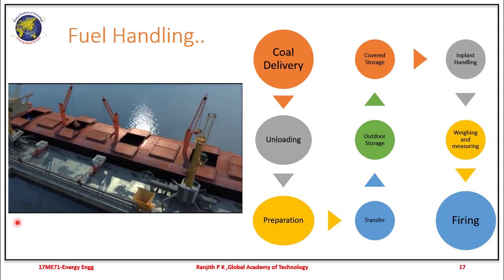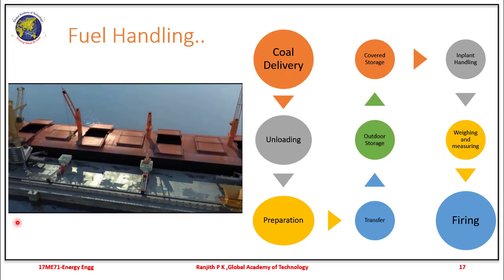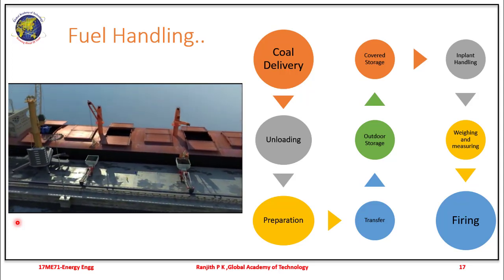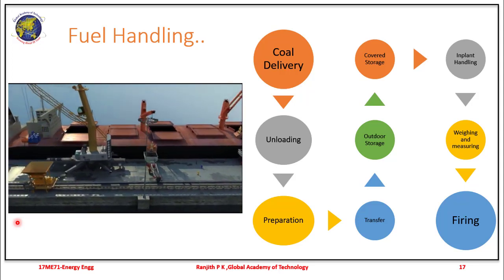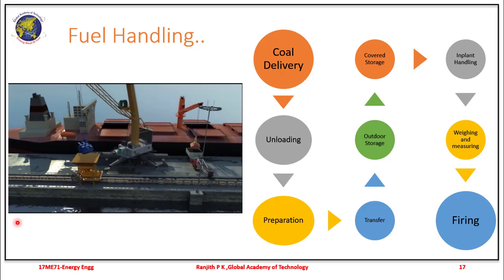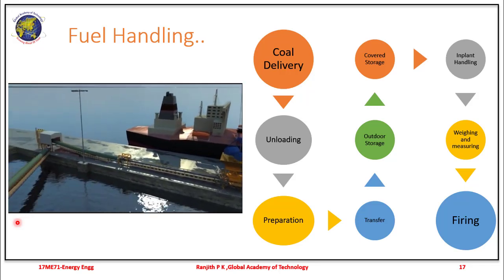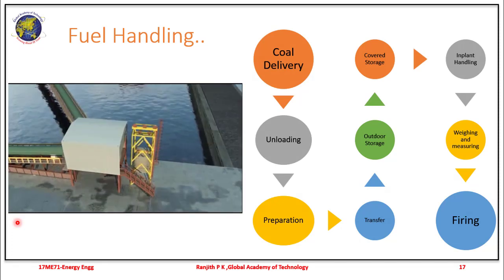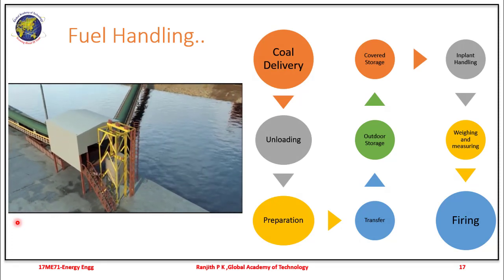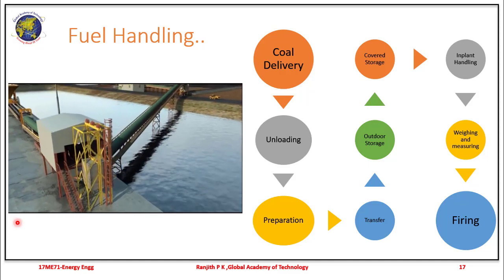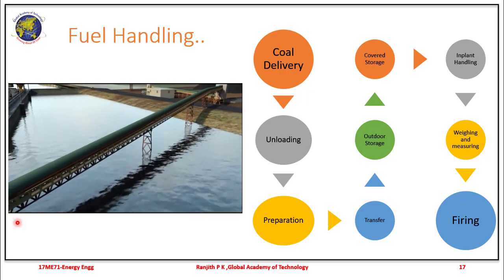Handymax vessels use their own cranes, vessel gear cranes, to unload the stock into smaller-sized mobile hoppers, which feed the berth conveyor belt by means of a belt feeder. The conveyor belt is installed between the rails of the hoppers, and it is equipped with a scale to measure the material flow and a metal detector. It also has an inline magnetic separator that removes undesired metal particles from the material flow in order to avoid tearing and other damage to the belt.